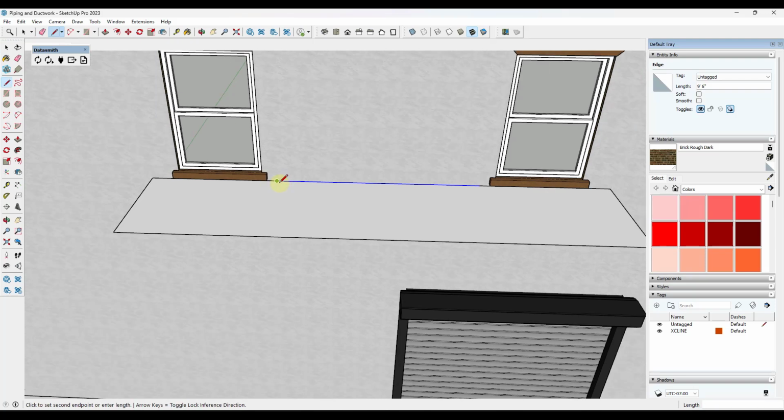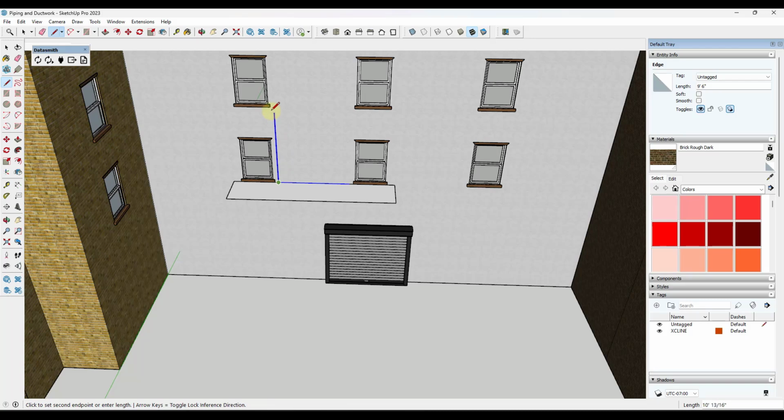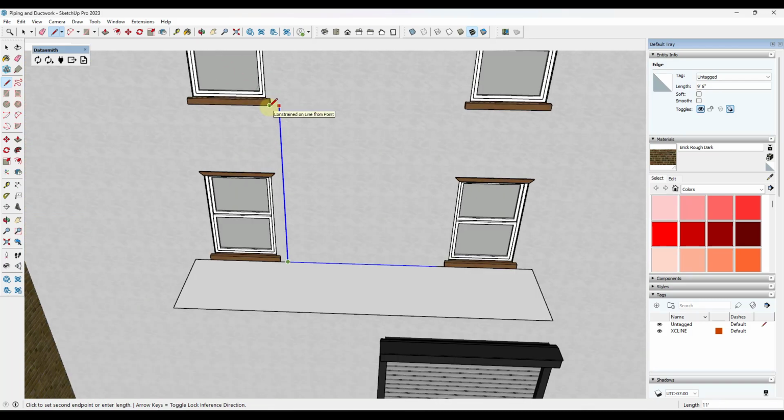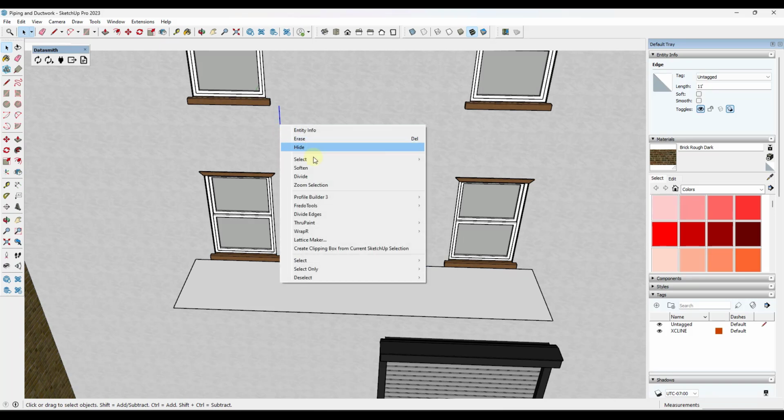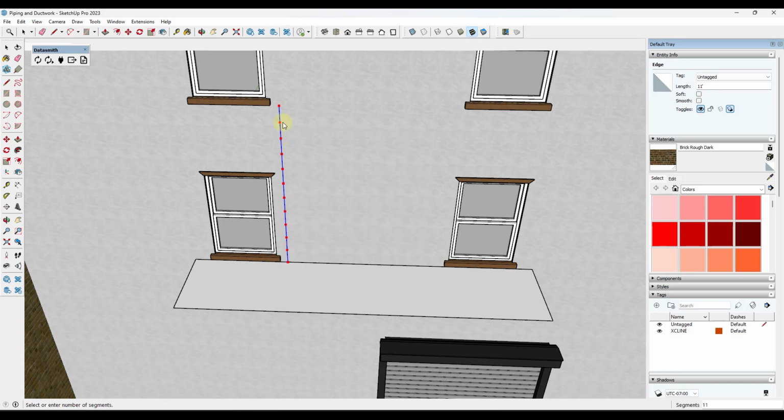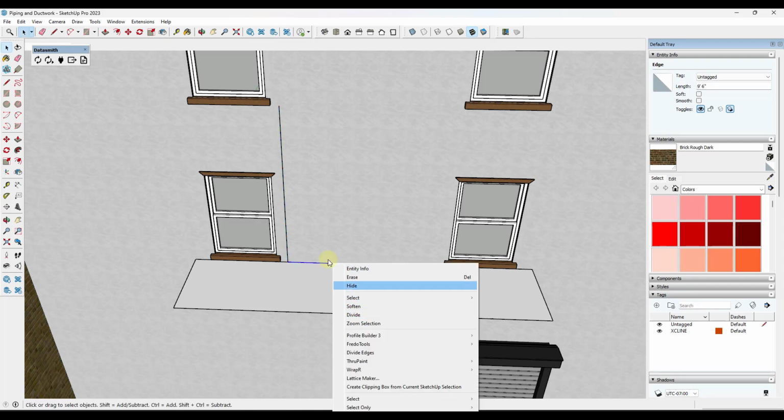And then we're also going to draw a line up that's going to represent the height of our stair, like this. Now I'm gonna right click on it, and I'm gonna divide this line. That's gonna allow me to figure out how many segments we have in here based on the riser height. For simplicity's sake, I'm gonna assume these risers can be 1 foot. 1 foot might be a lot, but it seems like fire escapes are generally steeper, so we're gonna go with this.